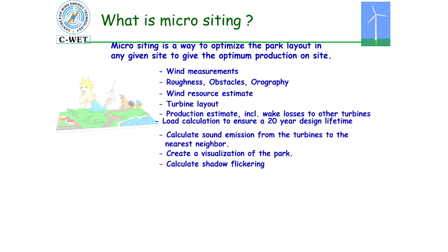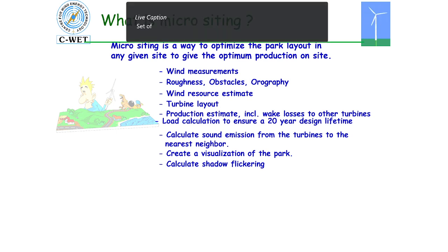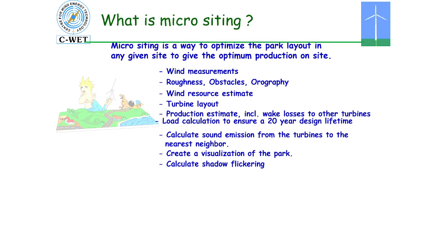I think for all these things, in India, what they do is they specify set-offs. What is known as set-off? Set-off is one times the height of the windmill plus one times half the diameter of the rotor. When it falls, it should not hit any residences, so there is a set-off for falling on residences.